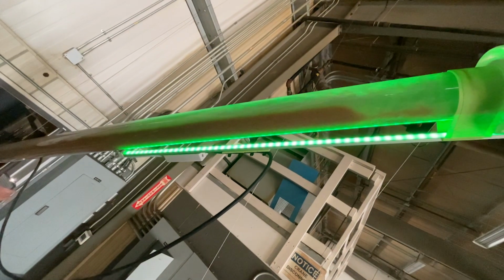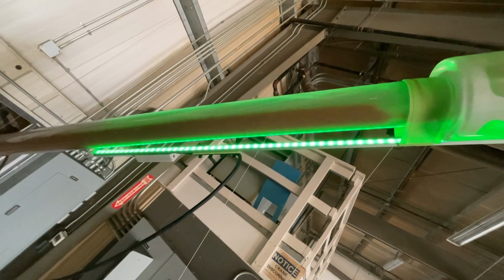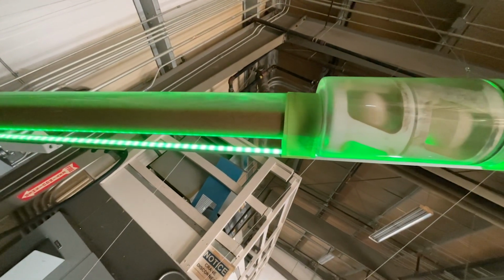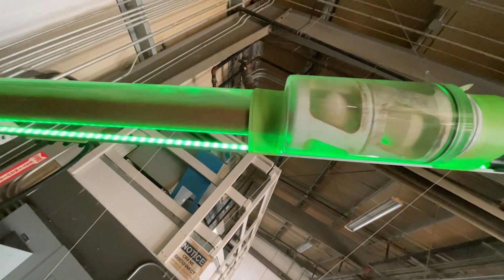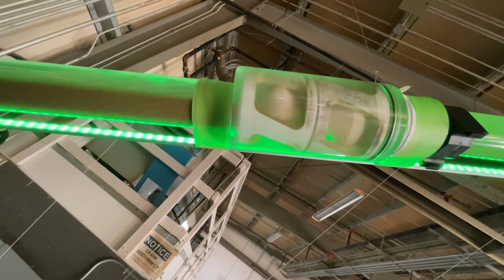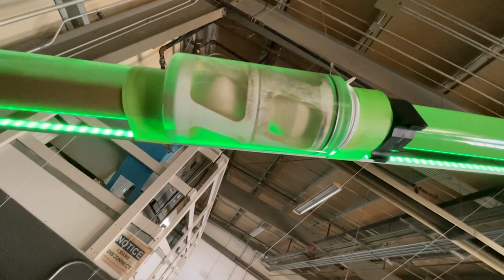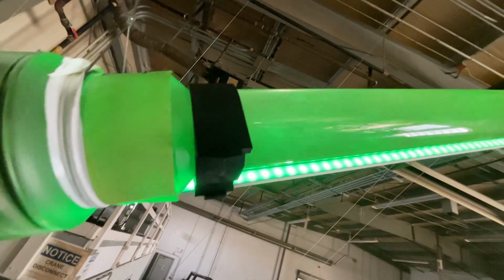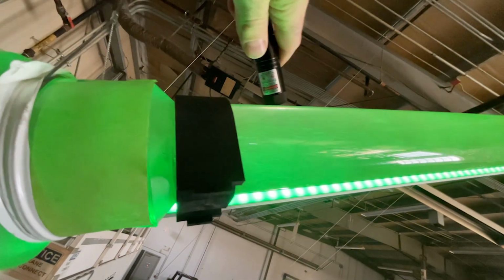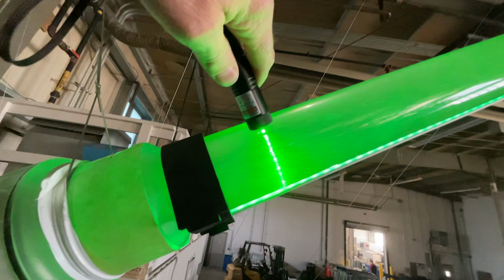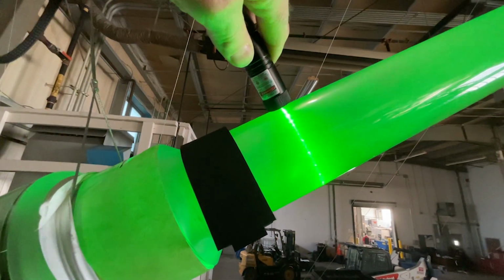In this case, what you're seeing is the HVS valve. So this is the first pump that you can actually pump down to 90 degrees. In the past, these balls fall off the seats around 45 degrees. So we've been limited in how far we can go. Now we're getting down to the bottoms of these horizontal wells, and with that extra fluid level, you're getting better pump intake pressure, and you're actually getting better production out of your wells.